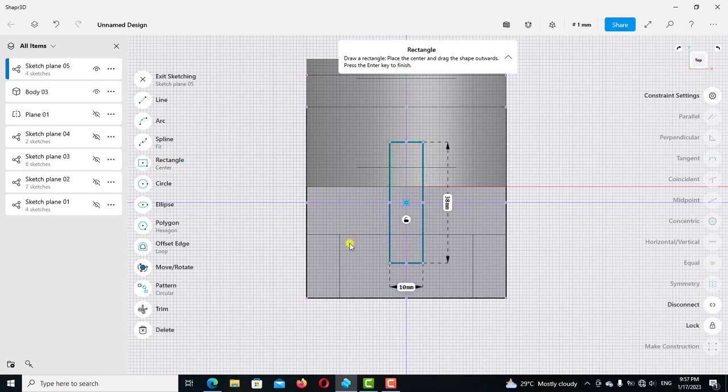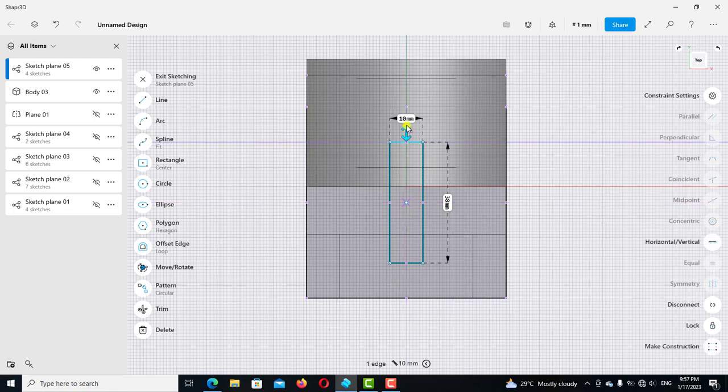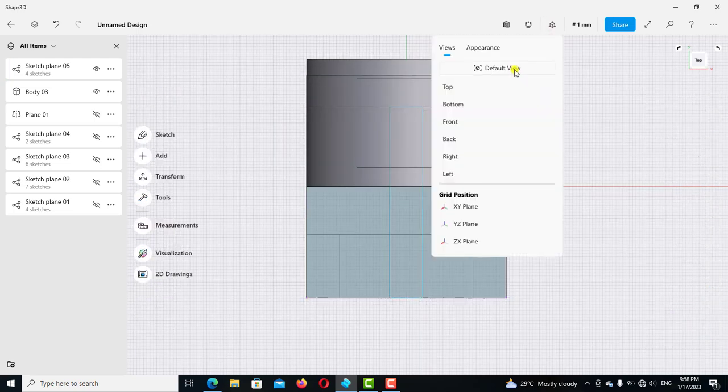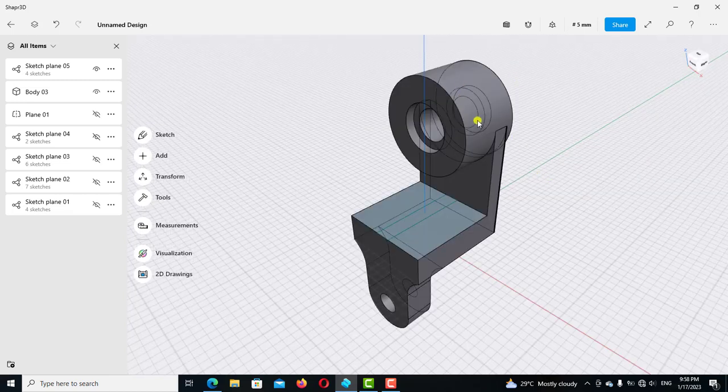and then I define this segment of the rectangle to 10mm. I will click the top segment, drag up the arrow to snap with the edge of the base. For the other segment also, I click it and take the arrow to snap with the edge of the base. The rectangle is created, and I have to create another one on the outside face of the cylinder.